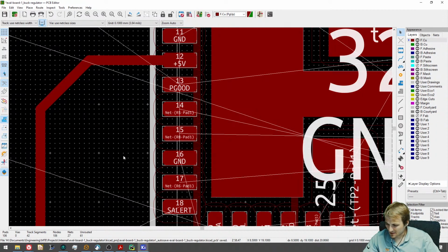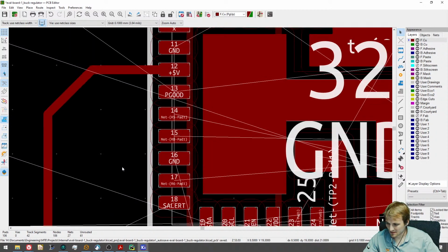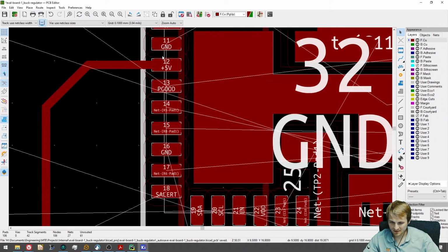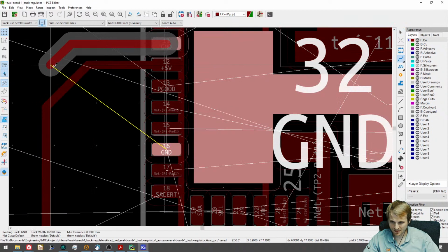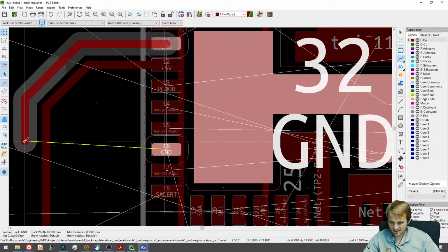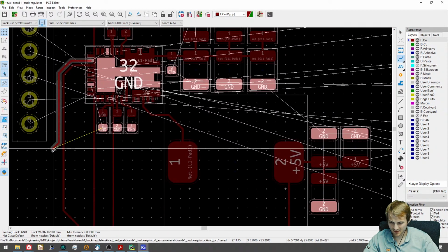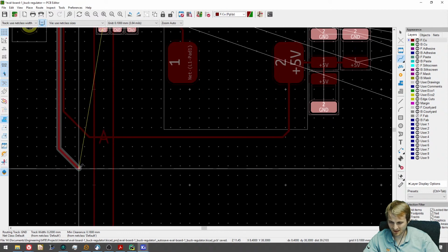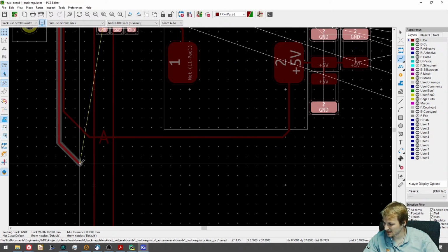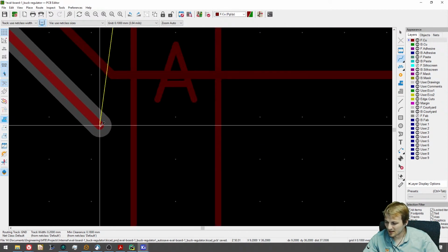Also, the differential pair should be far away from the voltage switch node, of course, and other signals throughout the length. So they want this to be a true differential pair going to the ground side, but the internal comparator will have an offset because of this when the IC heats up.